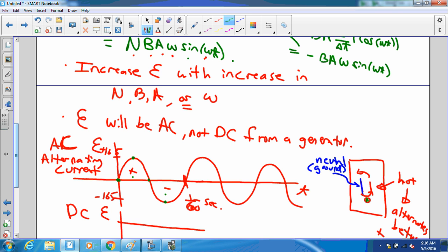So what can happen is this. Ground is a funny thing because we think of it as zero, but really it's relative to wherever zero is. So if you have two electrical appliances that are both, quote, grounded, but they are grounded to different grounds, they can actually be many volts apart from each other.